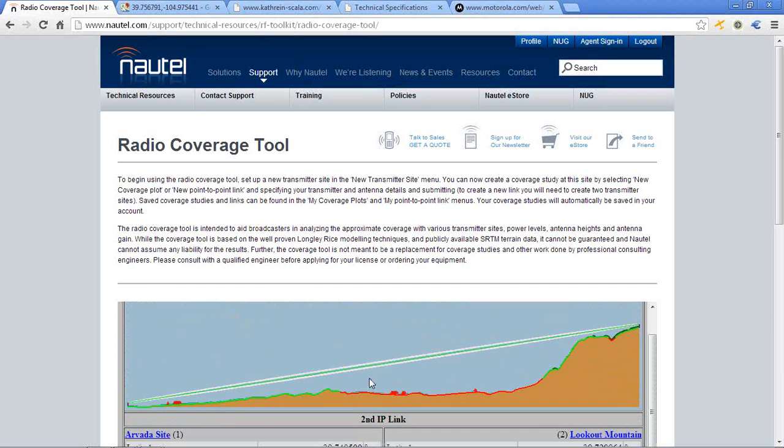Anything to add there, Roger? Yeah, in this case, if you want something more reliable, you can increase the antenna size. Yes. It's 20 dBi now. At that frequency we can have more. And antenna gain is a really good way to improve the performance, because in that situation you're actually reducing interference at the same time. The spot in the sky that you're illuminating, and particularly the spot of the sky that you're receiving from, is reduced. Yeah. So it improves your freedom from interference as well.